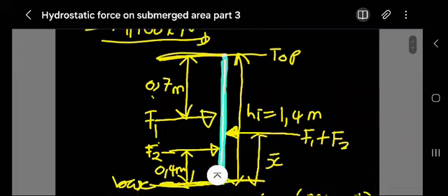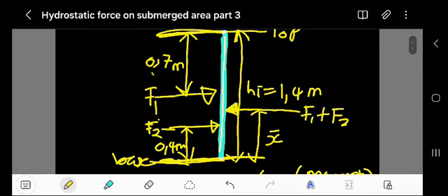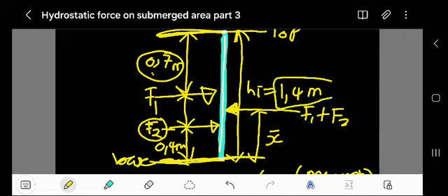So if we take moment from the top like that, as you can see, F2 will be equal to what? To 0.5, and what will be this distance, guys? That little distance, remember the whole distance is 1.4. Here we have 0.4, here we have 0.7. What is the remaining? We'll have 1.4, then I subtract 0.7 and also subtract 0.4. We'll be left with what? 0.8. Yeah, this is 0.8 meter.